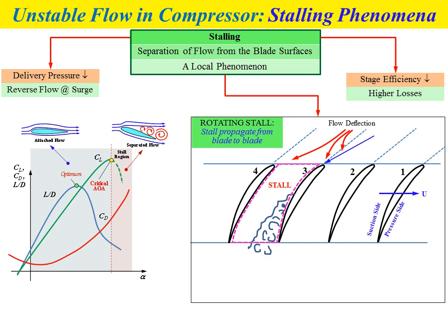However, in actual conditions, throughout the blade passage, we will have flow deflection. So the incident angle for the blade is not constant. At the same passage of the blade we will have angle deflection, so we will have different incident angles.